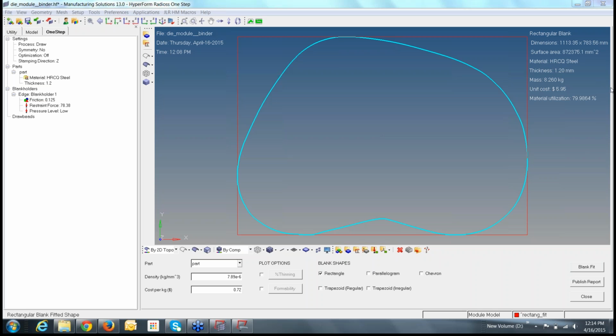Sorry, if it's a hard material, you need to scale it up by 15%. If it is a softer one, scale it up by around 20%, because that will expand a lot. That is useful when you are using this same blank for an incremental forming.